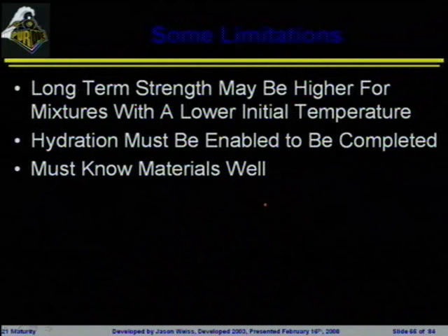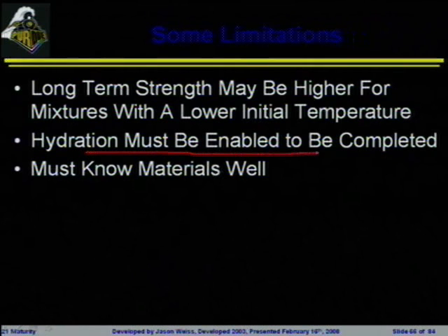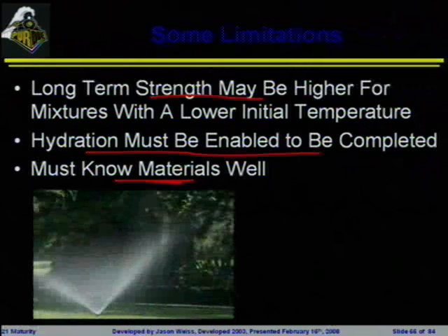There's a couple limitations, as we talked about last time. We said that the hydration has to be enabled to be completed. Therefore, you need to have water in the system. The long-term strength may be problematic for materials that go up to real high temperatures early on because you don't get the same long-term strength. And we need to know the materials very well, meaning we can't change our mixture proportions.